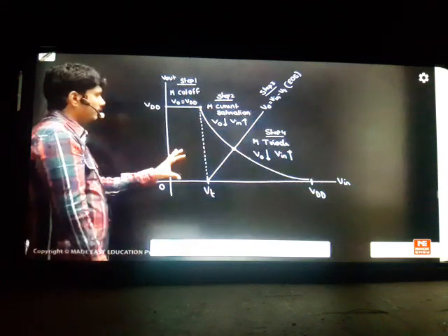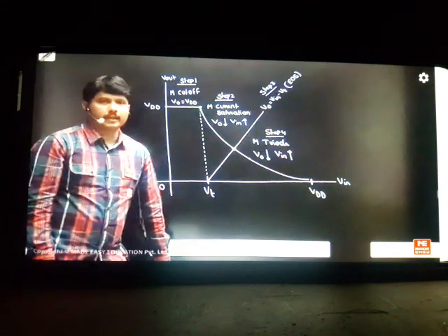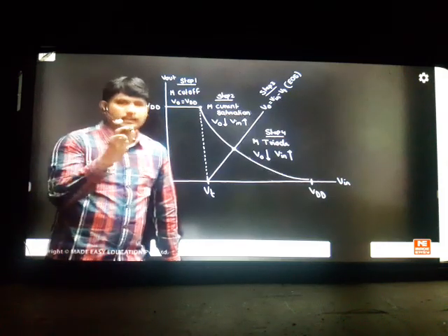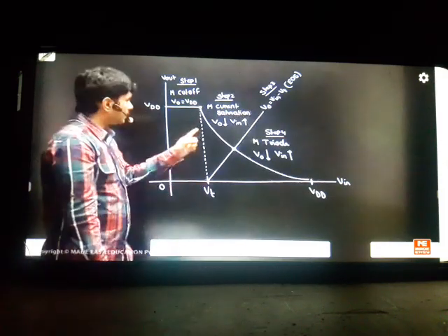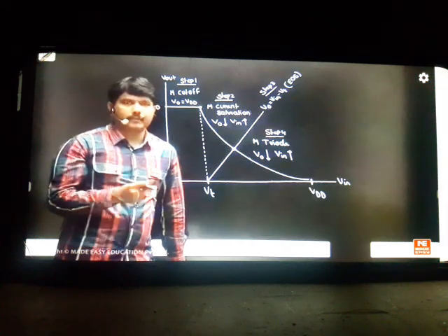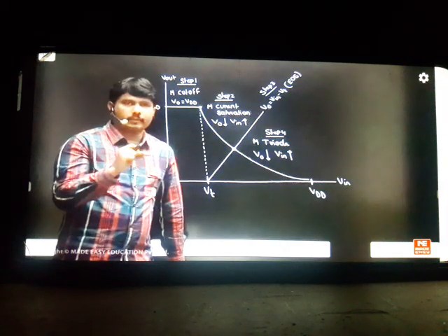So I think this graph is telling us it is not good behavior, not working like an ideal inverter. For an ideal inverter, the value has to fall at the center, and not only that, it has to fall linearly. But in current saturation, it is falling non-linearly. Whenever it falls non-linearly, you are taking more time to be in the active region. But for a good inverter switch, when going from on to off, you should not spend time in the active region.